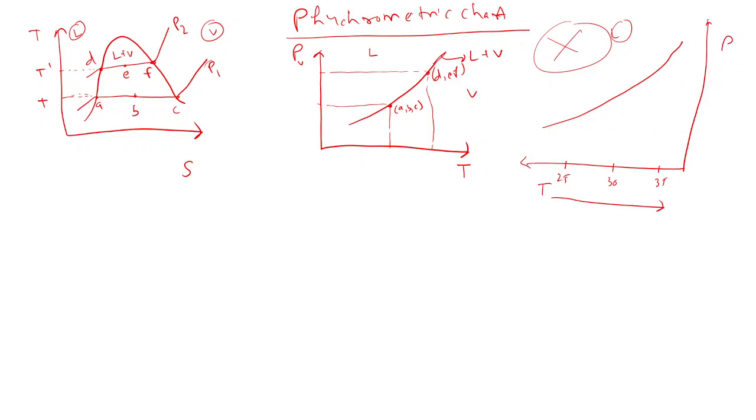So one thing, this is PV. So what is omega? Omega is 0.622 PV divided by PT minus PV. If you know PV, and for our atmosphere PT is fixed, 1.01325 bar, it is fixed.